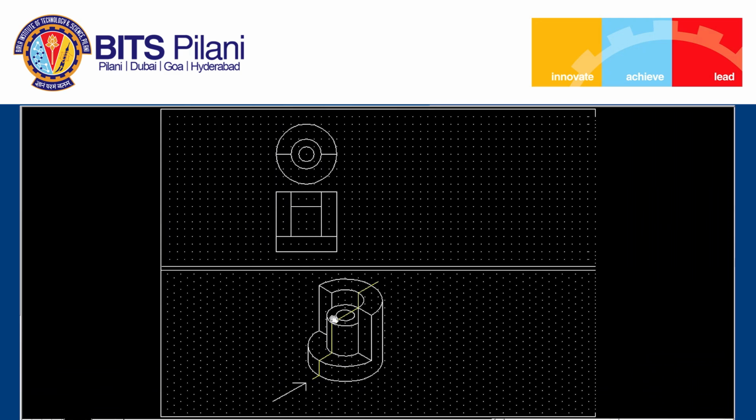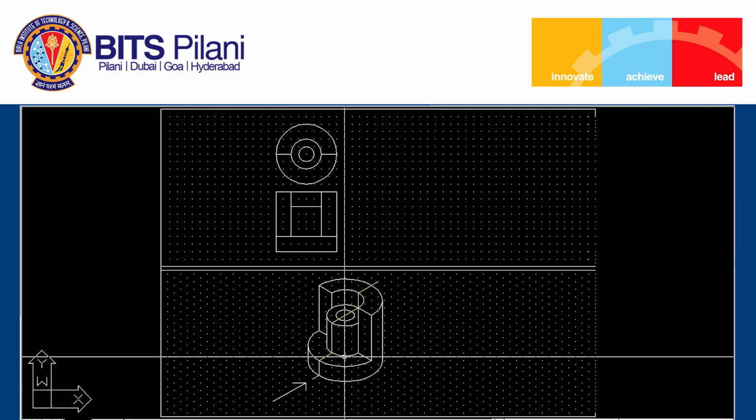Now further, if you see, there is a hole, that hole will be indicated with the hidden lines, because that is the inner curved surface. Okay, and unless specified, we consider the holes or slots to be throughout the object, if their height or depth is not specified. So here nothing is specified, so we assume the hole is throughout its height. So that we have to show, and that will be seen as a hidden line.